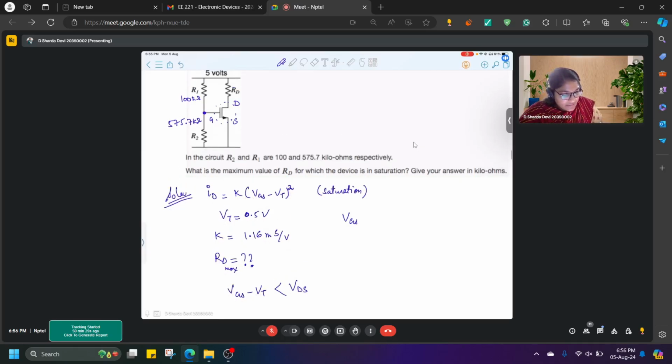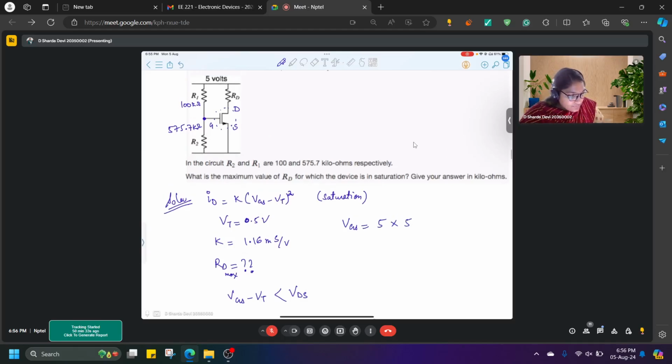How do we find the VGS? It is 5 into 575.7 upon 575.7 plus 100, right? So the VGS that we obtain is 4.26.